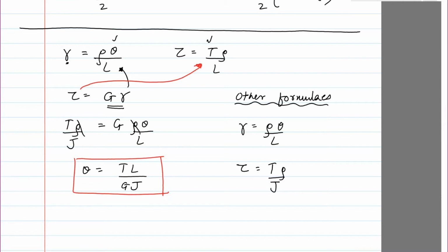And I think that's all to it. It's just these three. I think these are the three essential formulas which you need. Now, of course, you need to sub in rho equals R to get the maximum tau, and the same thing when you want to find maximum strain gamma.